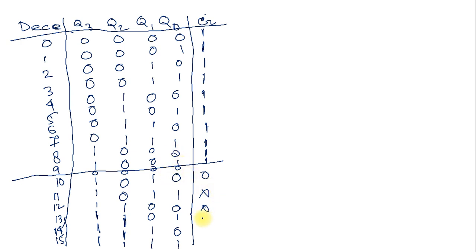So these steps are don't care. These 5 steps are don't care. Now from this we can derive another path also. Simultaneously, if we track this Q3 and Q1, when Q3 and Q1 both are 1, at that condition we can make this clear 0.